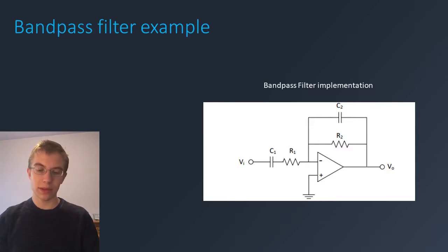At either end of the frequency spectrum, towards 0 or infinity, the output is attenuated heavily, ideally having a gain of 0. Within the cutoff frequencies of the circuit, determined by the poles of the system, the gain reaches a maximum, achieving the desired effect of selecting a band of signals.